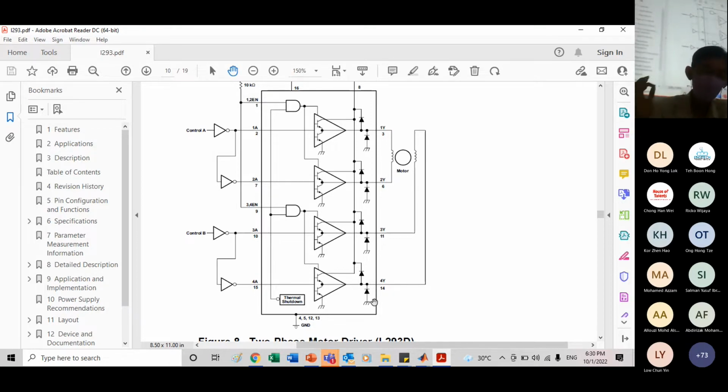So when I do demo testing or whatever, I always look at this, I will start to laugh. Especially those that worked yesterday, the most important one, this morning working, why? I look at it, no diode, no D, sure die lah. So sometimes they cannot understand why their friend's one can survive, because they are so lucky. They get the one with D, without diode. So don't underestimate this very small diode thing. In mechatronic and robotic projects, it causes a big difference.